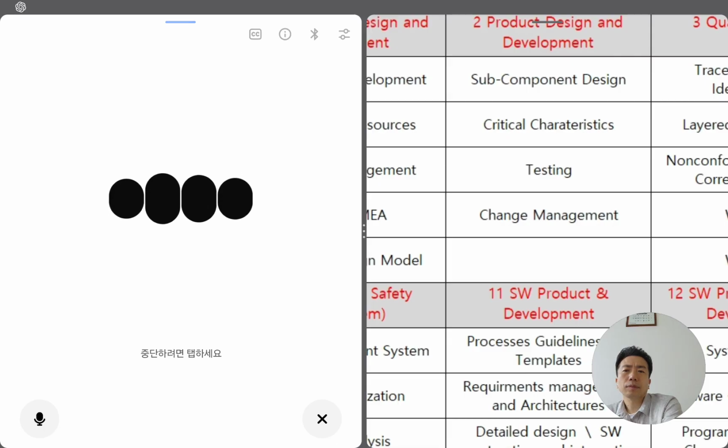Can you show me how critical characteristics are identified in your drawings and control plans? Supplier's short answer: We mark critical characteristics with a CC symbol on drawings, and we flag them in the DFMEA, PFMEA, and control plans. In the control plan, we also describe the special inspection or control method to ensure they are verified 100%. David, do you want me to draw up a small sample control plan line, just text-based, showing how a critical characteristic might be marked so you can visualize it more clearly?